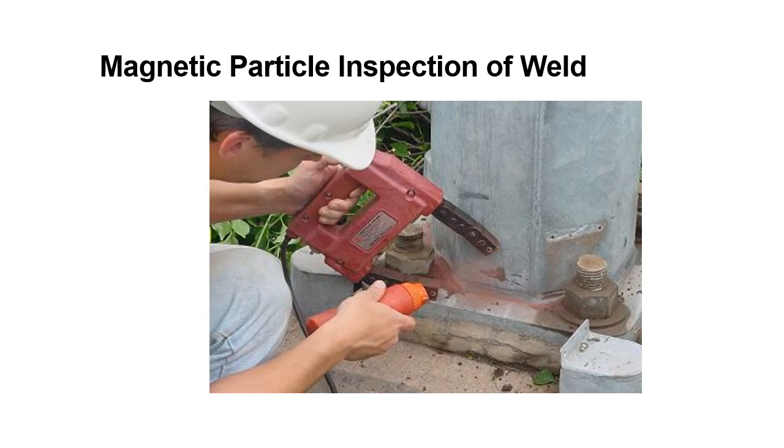Here we've got a picture of an individual doing a magnetic particle inspection utilizing a yoke, and you can see him spraying the powder. The powder's kind of got a red color to it so that it gives a good contrast.